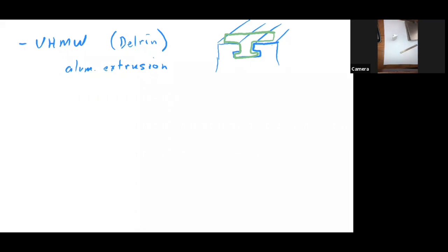In this case, the sliding surface, if you loaded it down with some sort of load, then you saw friction here, here, maybe it was shared there a little bit. You could put some moment loading on it, but you were really dealing with the sliding friction, which is classic static friction and dynamic friction. I think the frictional coefficient of the dynamic was about 0.17, keyword being about. So it worked pretty good when there wasn't load on it.